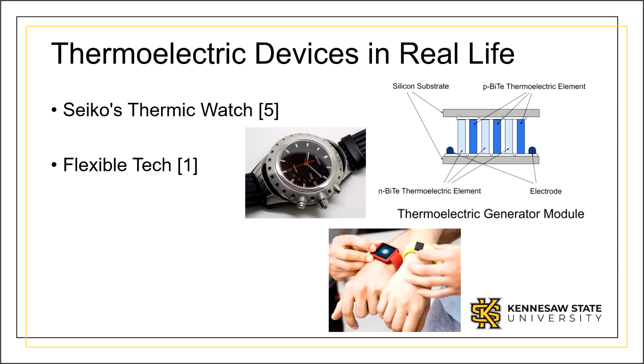The semiconductor elements in this device are connected electrically in series using liquid metal interconnects made of a non-toxic alloy of gallium and indium. The alloy provides a metal-like electrical conductivity and stretchability. The entire device is then embedded in a stretchable silicone elastomer. The silicone helps to increase the thermal conductivity to around 6 times greater.